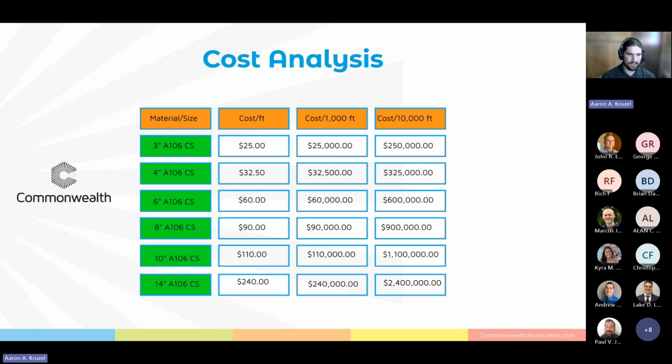It gives you a lot more ability to pinpoint precision, sharpen your pencils, get the most accurate answer, and at the end of the day, that saves money. If you oversize the system, sure, it's going to be a cost loss. It could cost a lot more if you oversize. But the alternative, if you undersize, is that you have to tear out that system. You have equipment failing prematurely. You have warranty issues. It's a lot worse to size it incorrectly.